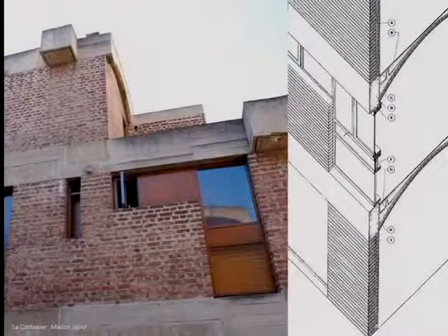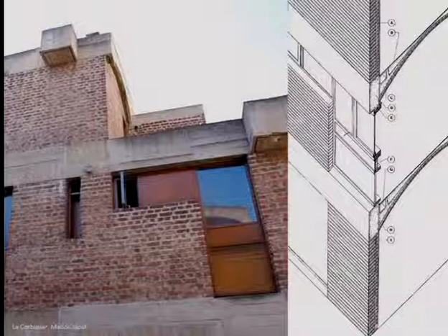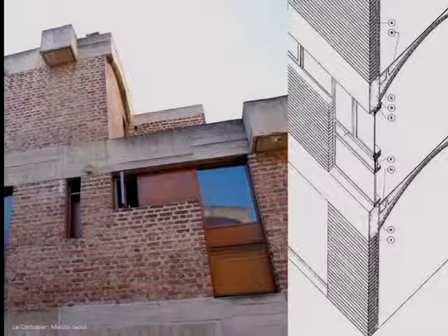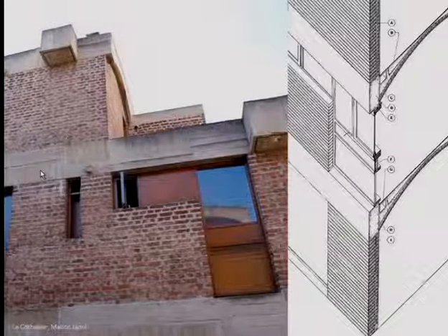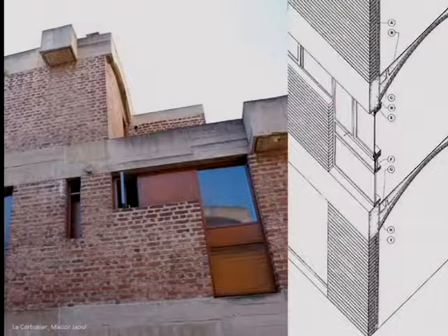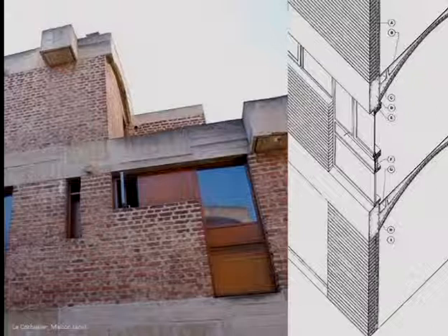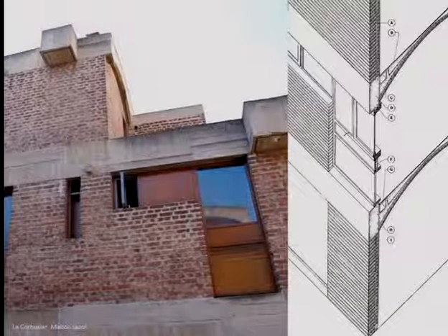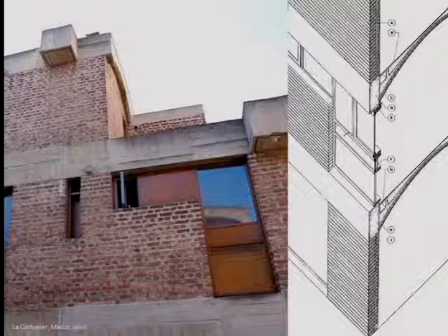Le Corbusier, why am I showing you this? For two reasons. The first is the color of the mortar. So you see that there is a concrete frame, so you see all the floors, they're visible in the facade. Then there is a frame of colors behind, probably one column running here. And what happens is that the mortar is done probably with the same sand, so that the color is very similar to the one of the concrete. And the masonry wall doesn't look so dark. So they actually look very homogeneous. So the final result is very homogeneous. Okay, so this is one thing.